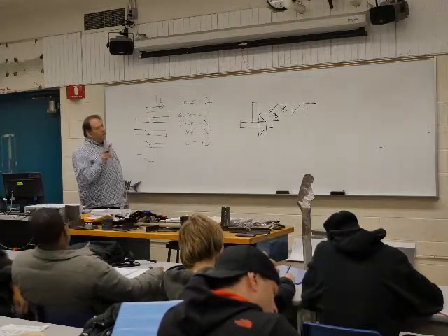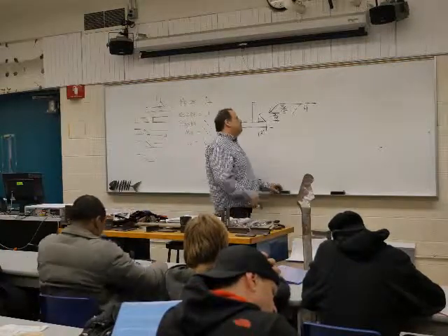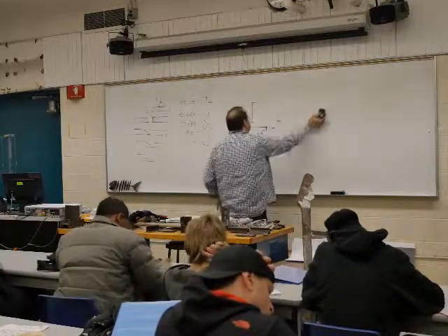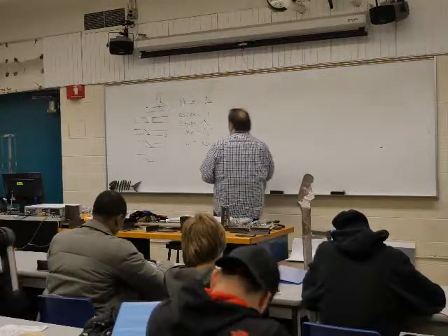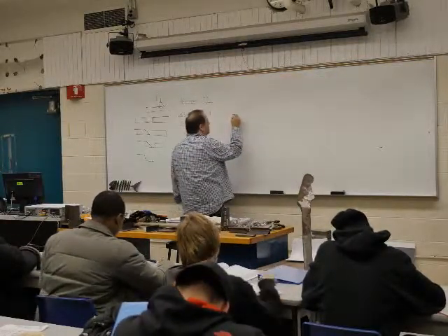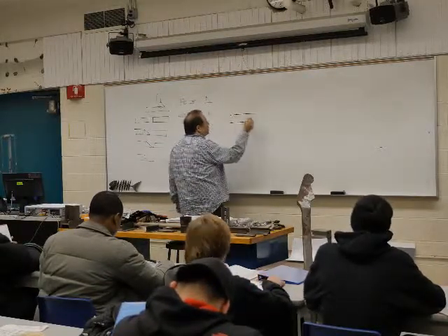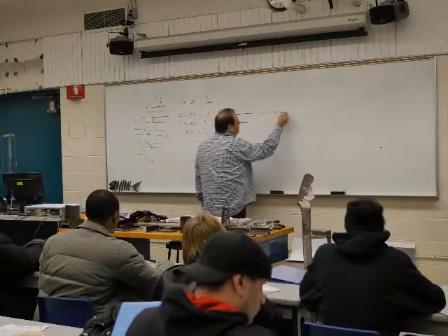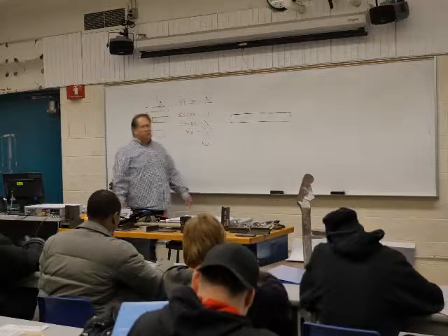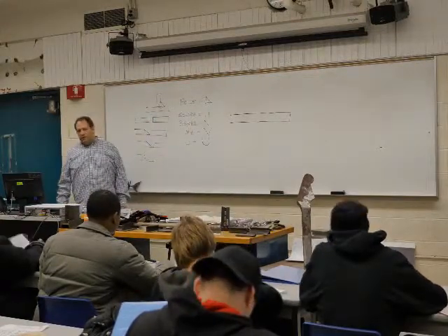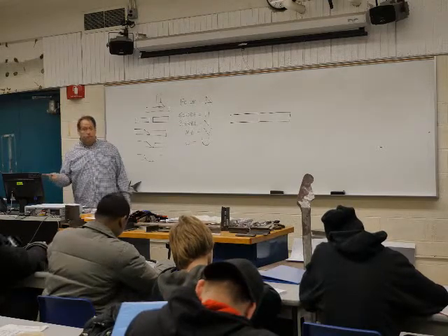All right, so let's go to the groove. Let's start dealing with grooves for a second here, because we'll get back to this one, as there's something I want to add to that. Now the preparation for your weld is not going to be on the print, it's going to be on the symbol. So your butt joints will always look this way, and that would generally be a square, but you have to look at your print symbol to tell you what the preparation is.